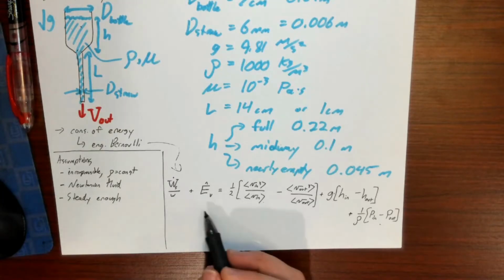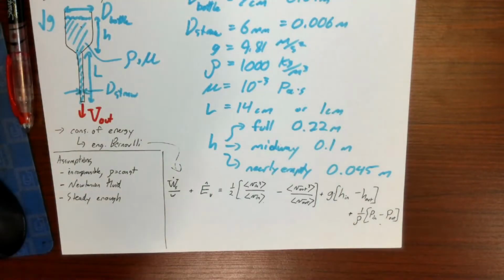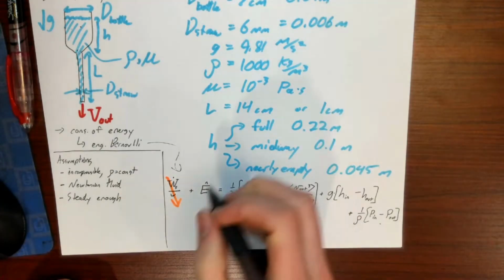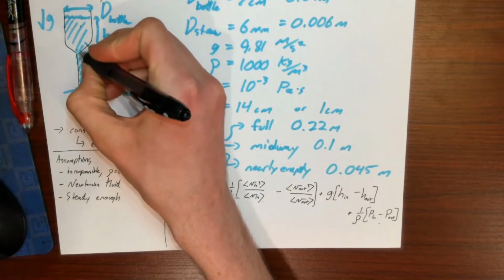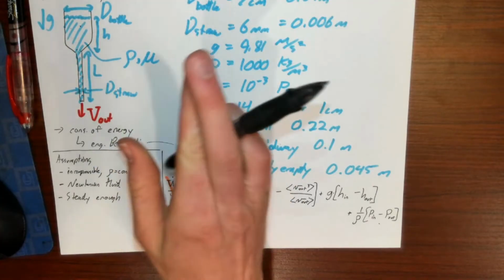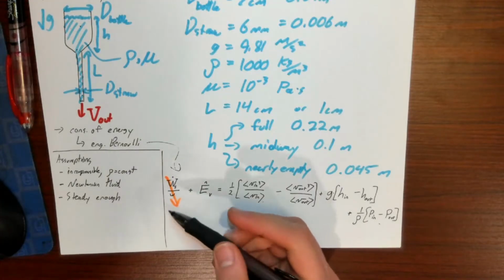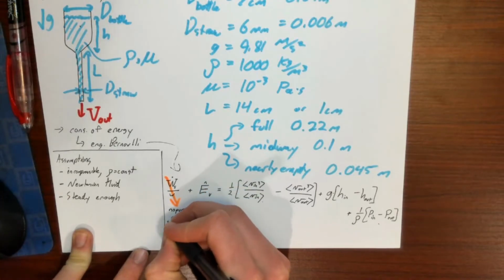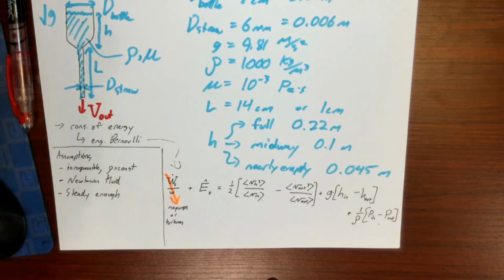All right, one of the first terms that we might be able to square away or get rid of is this term right here. If you recall, this was the shaft work term. If we look at the system, we don't have any pumps. It's not like I stuck a little secret pump in the long straw one, right? There wasn't a secret pump in there, really, I swear, that was pumping that fluid faster. So we don't have any pumps or turbines, so we can get rid of this term.